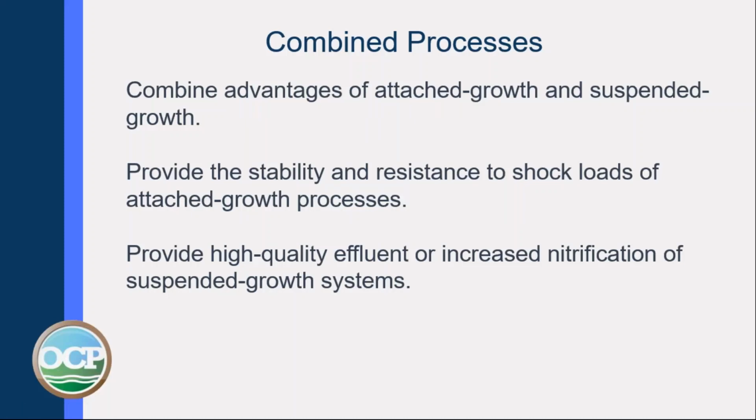Combined processes. They can combine the advantages of attached growth and suspended growth systems. They provide the stability and resistance to shock loads of attached growth processes. They'll provide the high quality effluent or increased nitrification of suspended growth systems.